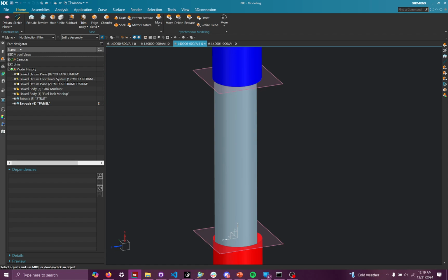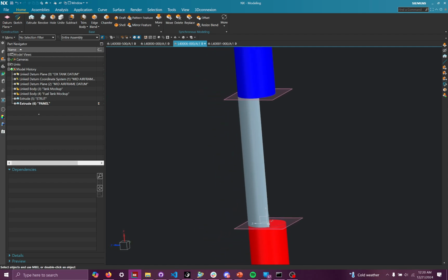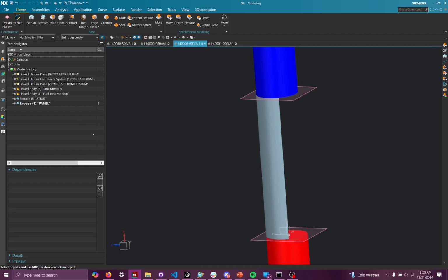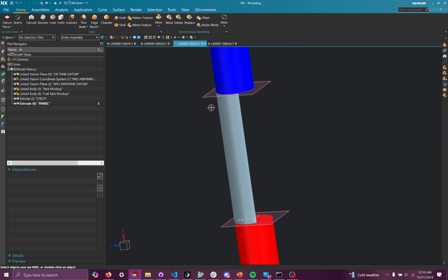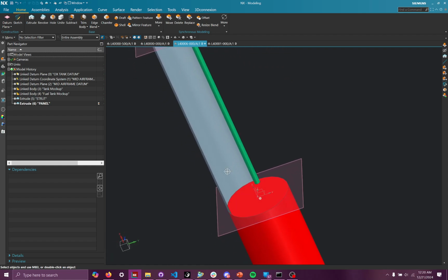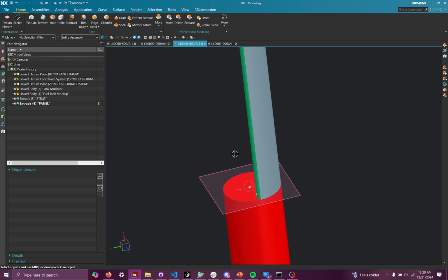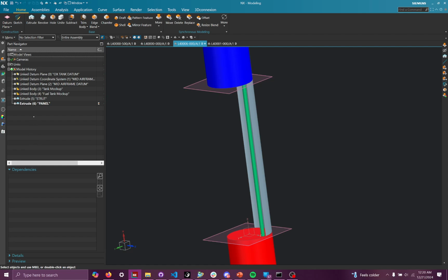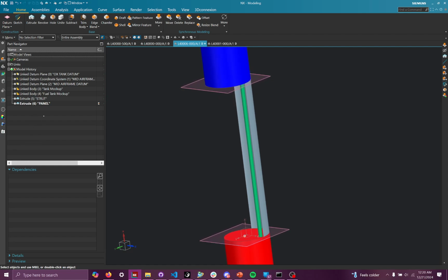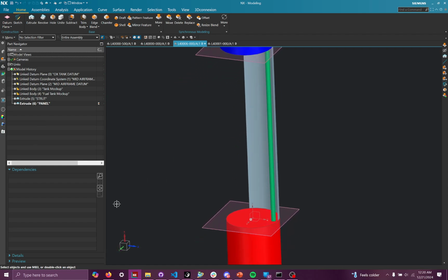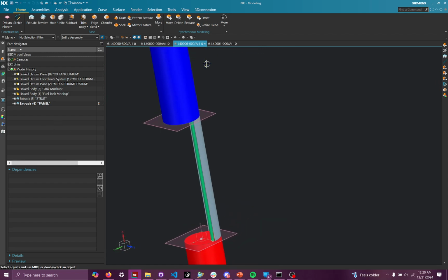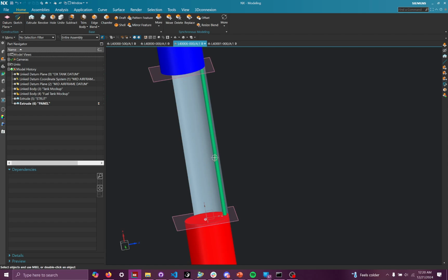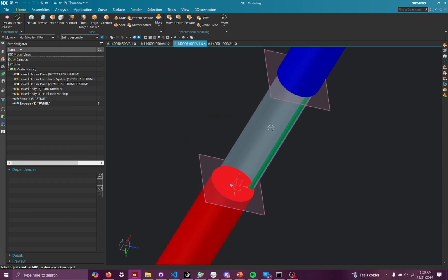And this is something I will be quite passionate about, is naming all of your features. I know it can be pretty painful to do, especially if you have a very complicated part that you're modeling, but it is very worth it. It's not only worth it for you as you go through your modeling tree of like 100 different features and have to find the one extrude that you did a week ago and change one value for it. It's also useful for other people who may be checking in on your part to see how things are done or make a change.